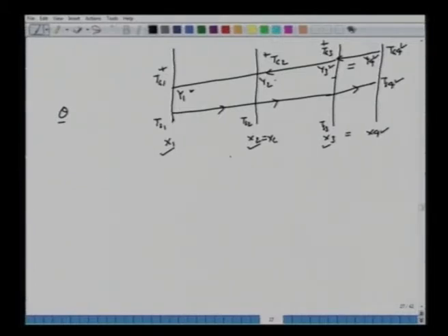All right. So when we want to calculate the enthalpy, how do we calculate the solid enthalpy at any location between 1 and 4? Hs will be equal to CPS, the specific heat of the solid. If we choose 1 kg of solid, it will contain X kg of moisture. So we'll have CPW times X, the moisture content, times Ts, the solid temperature at any location, minus some reference temperature. Generally, you can choose the reference temperature as 0. There's no harm in this, as long as we are consistent.